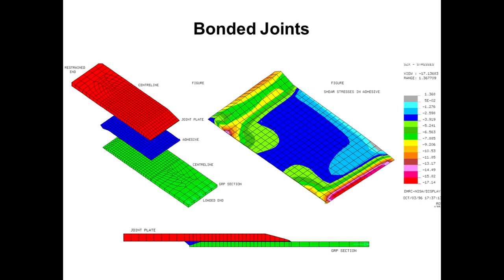What we're looking at is something that's often asked, which is, okay, you're making FRP sections, and you're then having to connect them together. With most materials, we already know a lot about connections and how we do it. With FRP, they are bonded; they're effectively glued together with adhesives, and you will miter those connections. So you're almost looking at kind of traditional joinery details in order to connect them together.